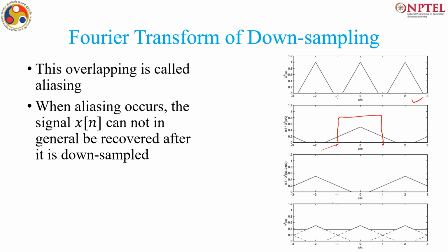And this is obvious because suppose my signal bandwidth is say 100 and I have done sampling at 300. Now, this is safe because this is above Nyquist, which is 200, twice of this bandwidth.